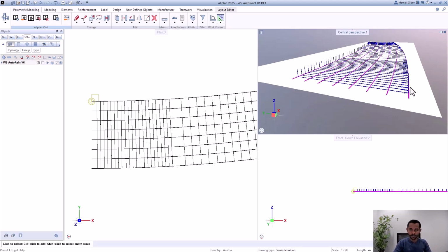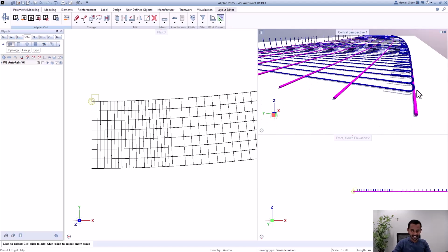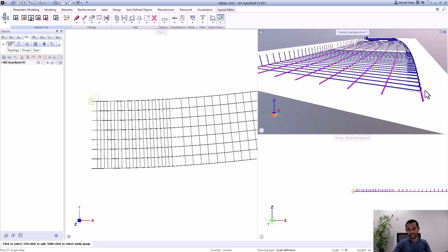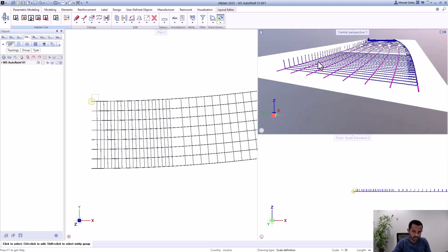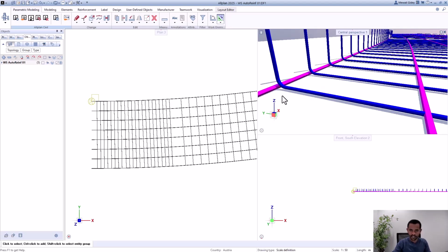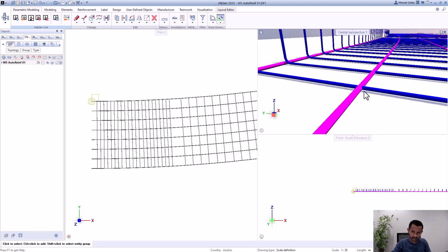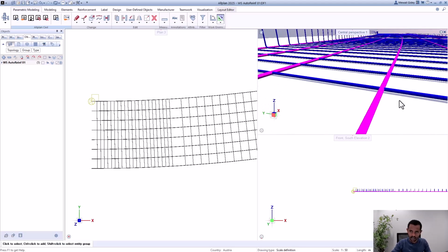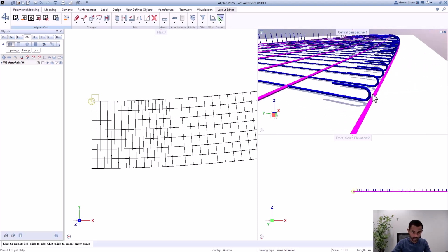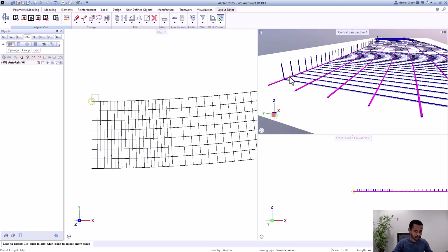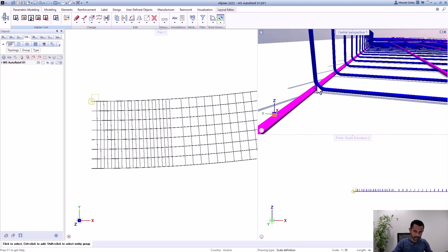But still, we have one big issue, which is the clash. You could see that there is a clash. A clash is quite important because it really changes the length of the bars. For this case, this one was modeled from this end point to that end point, and this has a lot of issues. There are clashes here in the middle, as you can see, and there are also problems because the bars should normally go all the way. For example, the transversal bars should go all the way to the back and hug the whole longitudinal bars. Here you can also see that.